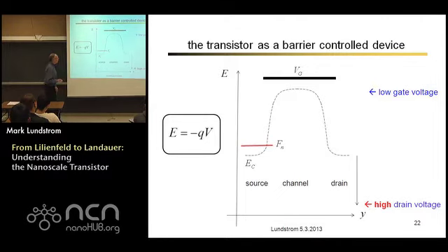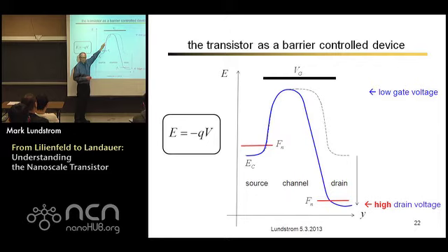But if I have designed the MOSFET properly, if I paid a lot of attention to 2D electrostatics and short channel effects, and this is difficult to do, then the barrier that stops the current from flowing has not changed. It's still the potential on the gate that controls that barrier height. Even though we put maybe a volt here on the drain, that lower potential there wants to pull this barrier down. But if I've designed things right, the gate is going to hold it up.